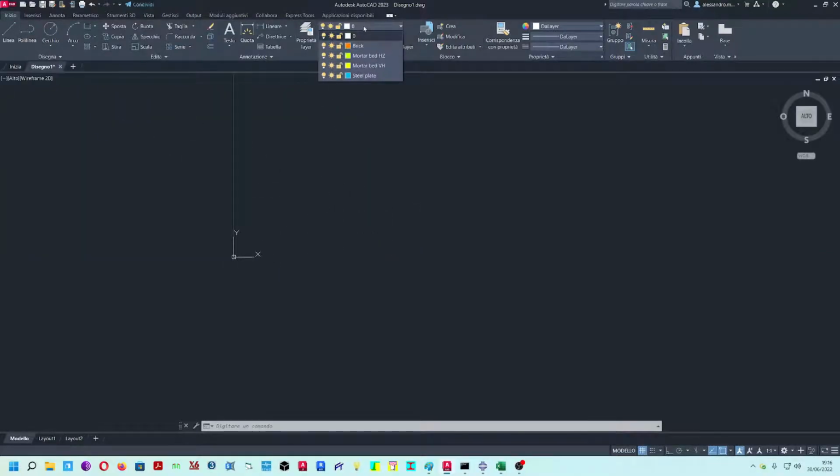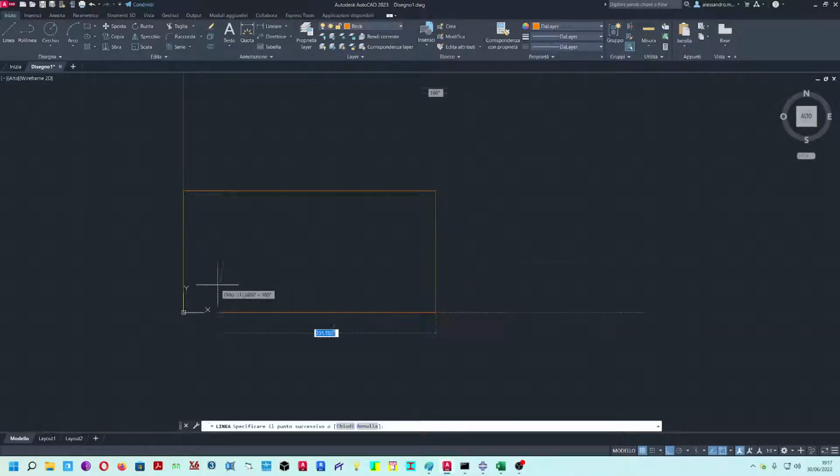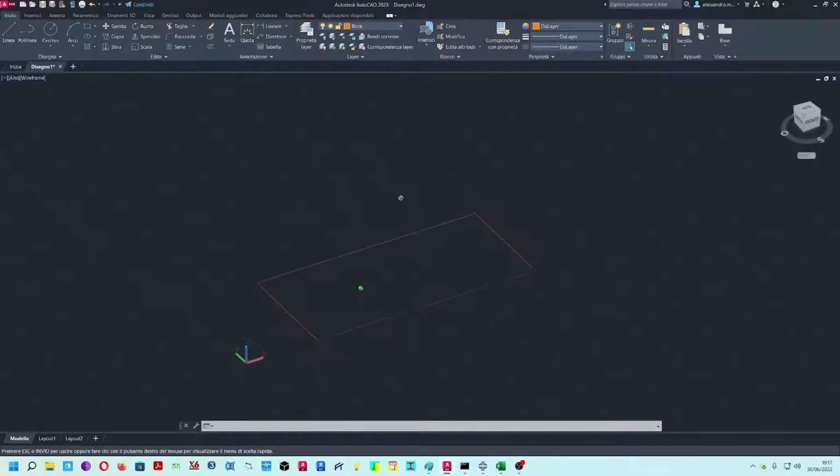Okay, first things first, we start with the brick, and I'm drawing in millimeters. Abaqus does not have units of measure. You have to understand how the various units relate to each other with a criteria. Then, okay, so we start with 250, 120. Okay, good.